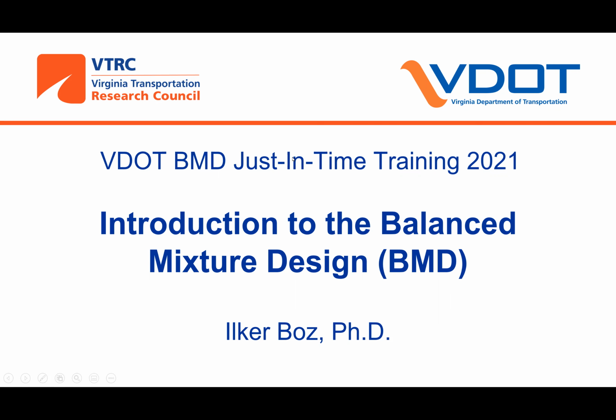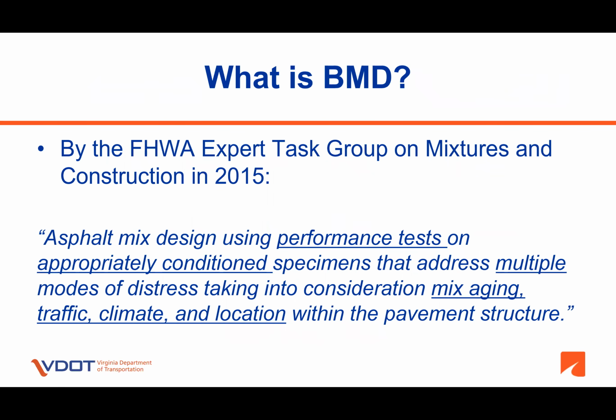In this presentation, we are going to go over the basics of the BMD concept. What is balanced mix design? Balanced mix design is an asphalt mixture design methodology that utilizes performance tests on appropriately conditioned specimens that address multiple modes of distress, taking into consideration mix aging, traffic, climate, and location within the pavement structure.